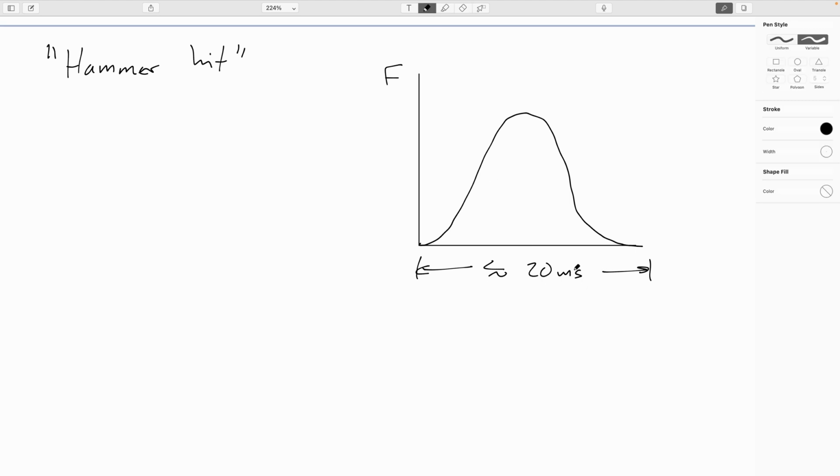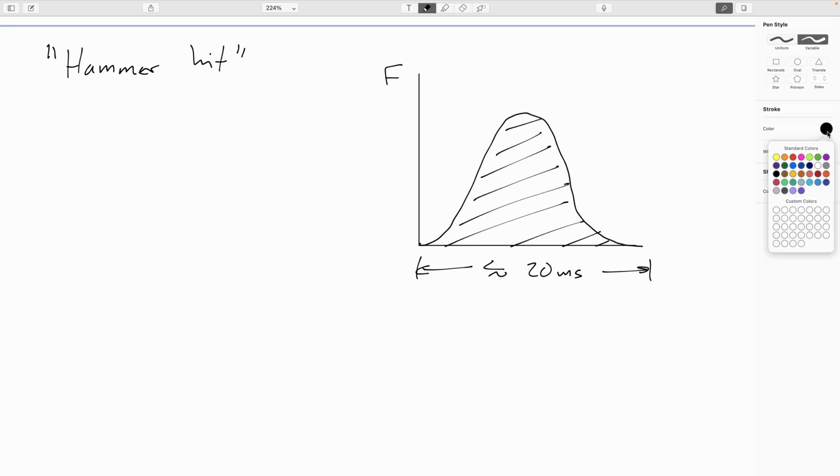So a lot of times it's very hard to get a clue of what the maximum force might be. In an engineering lab bench, test bench kind of situation, it's often fairly straightforward, though, to measure how much the momentum of the thing changed. And you can use high-speed photography to figure out how long it was in contact to get this time delta t right here.